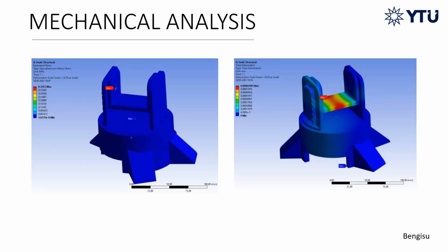After the mesh analyses were completed in the ANSYS program, von Mises analysis was performed. You can see the maximum equivalent stress in megapascal on the left. On the right side, the place where the maximum total deformation is seen is determined as the bottom of the camera. According to the 3D filament material selection, a deformation not exceeding the yield stress was observed.